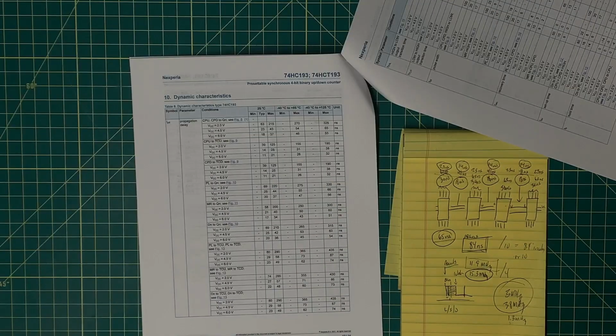Now, I'm kind of hampered by a decision I made early on, and that was to deconflict load and increment and decrement by having them all tied to the same signals going off to the register. If I had it to do over again, I would probably separate out the load from increment and decrement. That way I could have separate timings for each of those and not have to worry too much about it. But I've made my decision on that, and I've had the boards built and ordered, and I'm starting to assemble those, so I'm going to live within that constraint for now.